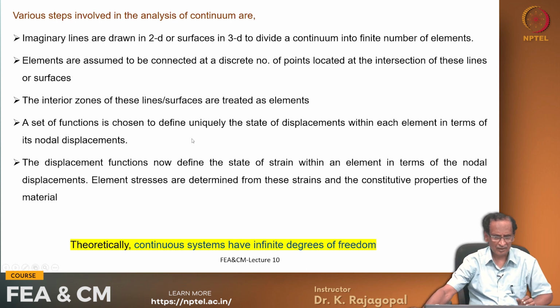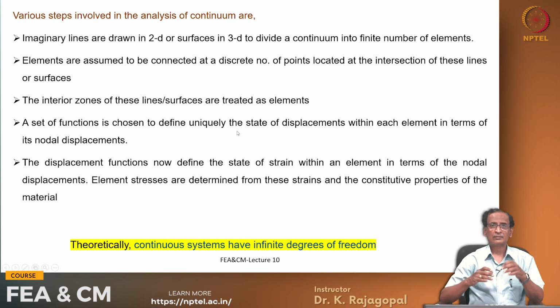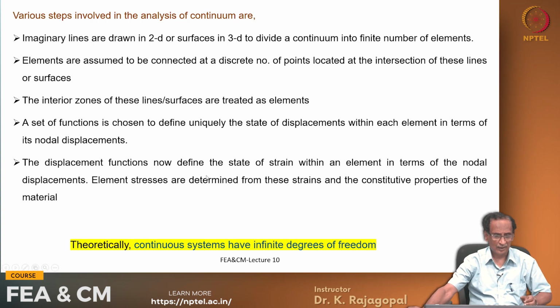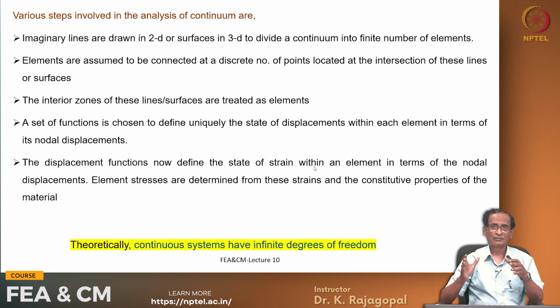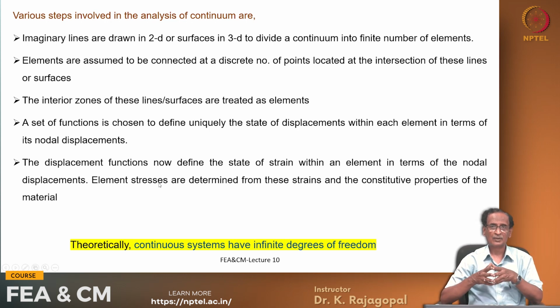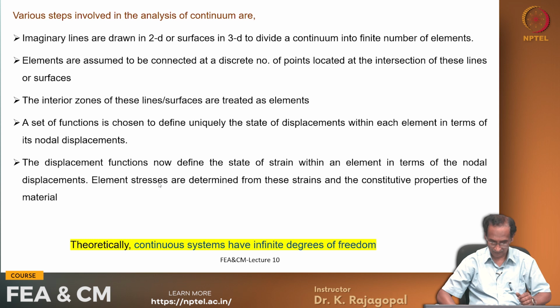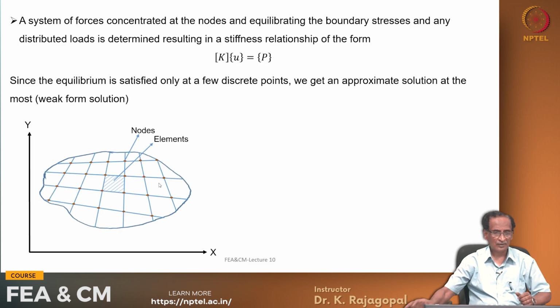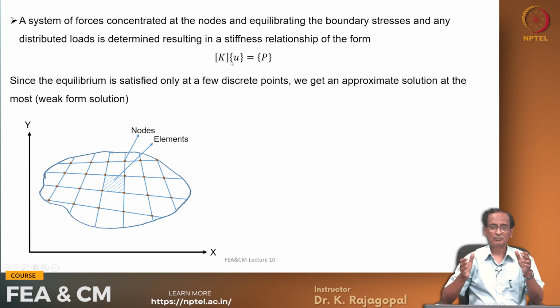And now once you choose some function, this function can define the state of strain within an element. Like once you have a function for the displacements, the derivative of that will give you the strain. Okay? And so these strains will be in terms of nodal displacements. Then once you get the strains, we can get the stresses.